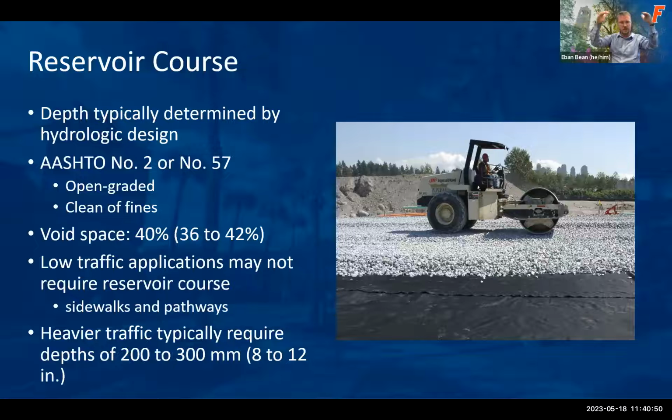So what becomes determining is the hydrologic design and having enough storage to meet your water quality goals. The reservoir course is typically number 2 or number 57 open graded stone. The open space ranges, but it's usually around 40%. That's where our volume of water stays.